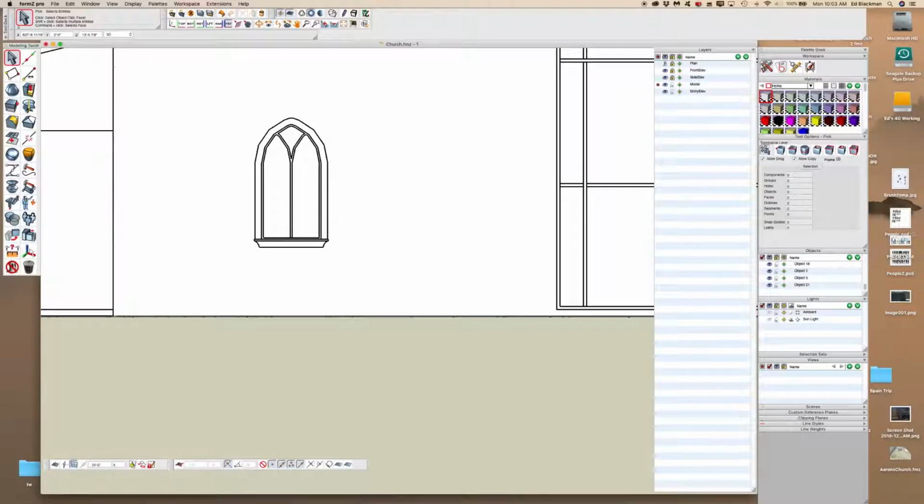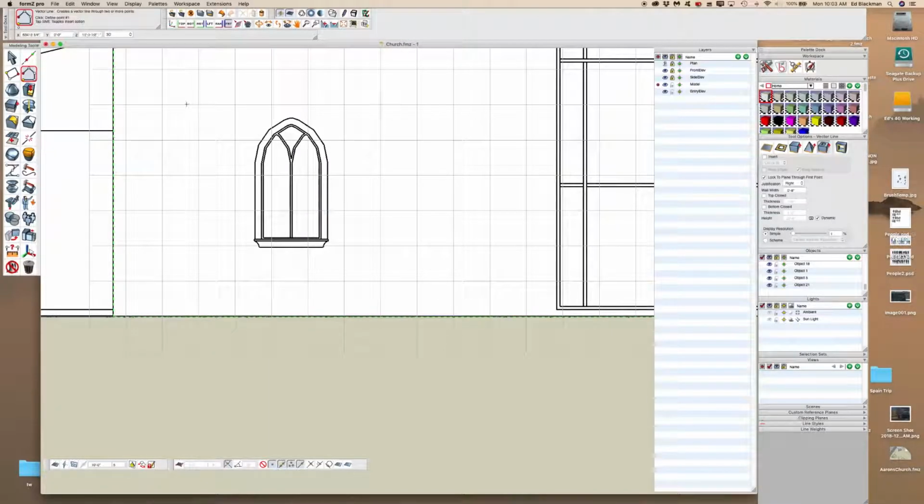So as you remember, we have a polygon tool over here, which means we can draw multiple faceted lines. And so what I want to do is draw a line, a 2D line. So that's this. I'll go over to the tool options. This is this 2D tool here. But I don't want that plane to be hovering in space. I want to insert it, literally insert it on the surface of that church box that we've created a while ago. So I'm going to click Insert.